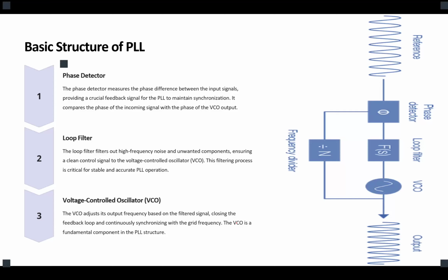And the VCO comes in at that point. We have our new frequency. The VCO would create a sinusoidal signal with the detected frequency and send it as a reference to our PWM.